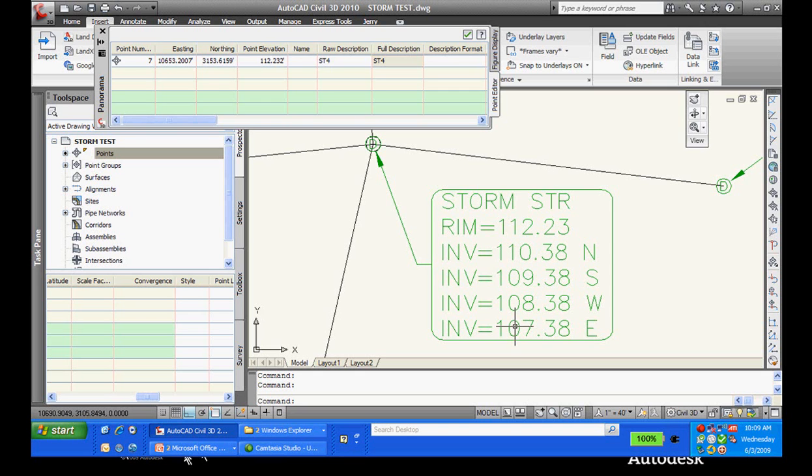What would happen is, the question is, where would the survey people enter that data? Depending on their collection device, if they get exported as an ASCII file, the number that they shot originally, and then those attribute values would be ASCII. So if they do it in a collector and export it into Excel spreadsheet, ASCII file, text file, that's all we're looking for is rows in like common limited file formats is all it needs to be.